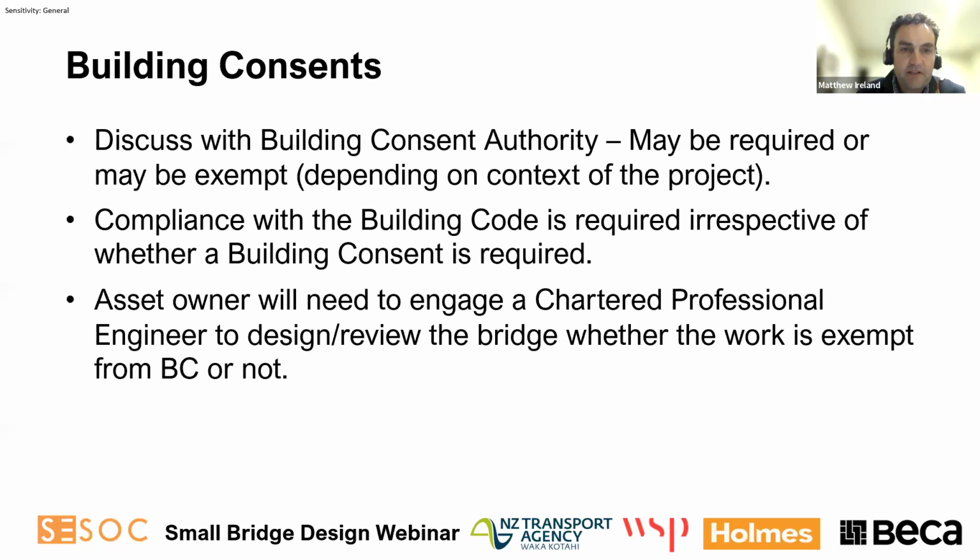So now just to go to building consents. For bridges, a building consent may or may not be required. Within the Building Act, there are a number of avenues for bridges to be exempt from building consent. Geoff touched on one at the start there. For bridges less than 6 meters long, along with some other conditions, there is a section in the Building Act that specifically exempts these from building consent.